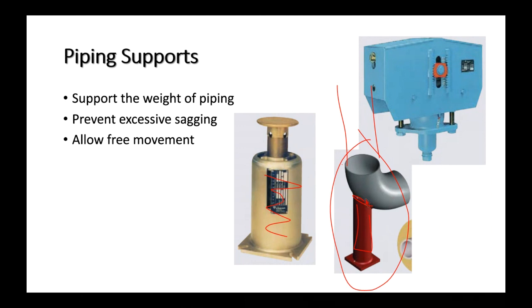And in case there's damage to the pipe on the inside and it starts to leak, what happens if that leak or that crack occurs right where the support is? Well, what we're going to do is have a little hole in here somewhere, and the hole is called the telltale, and that way we're going to know if this thing has started to leak.